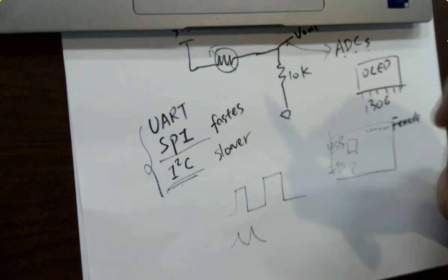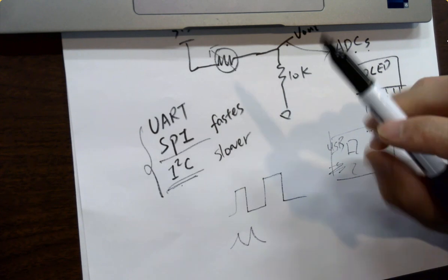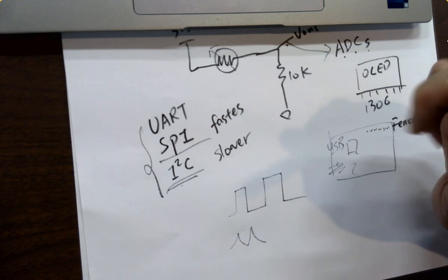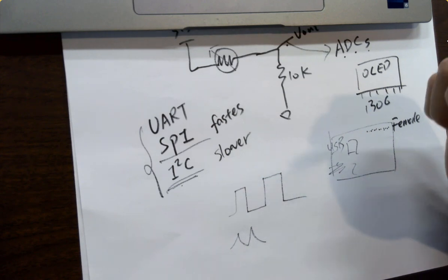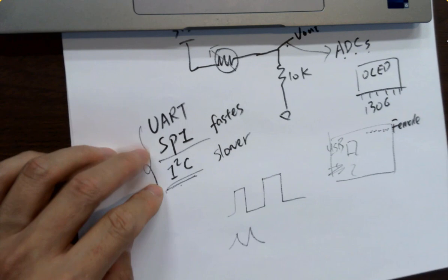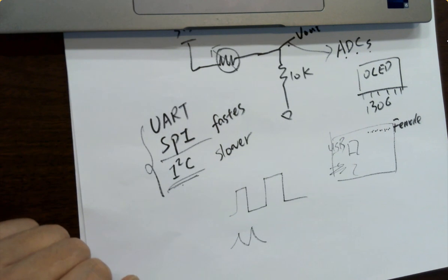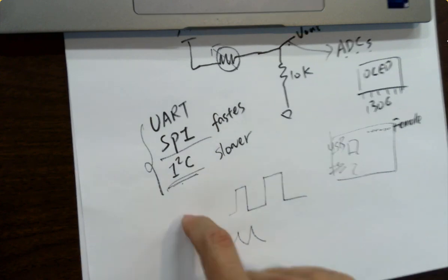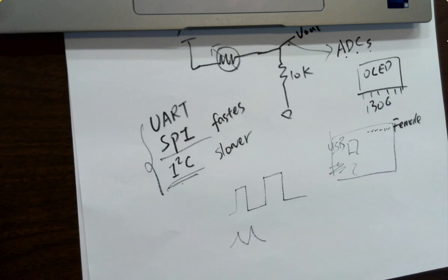If I want to transfer temperature data from a hot tub in Pagosa Springs over a 100 meter cable to a data center mounted to a pole on their property, do we want to use SPI or I2C? Is it through a wire? Yeah, it's a cable. Oh, a temperature sensor, just a sensor, doesn't have a microcontroller on it. It's just a little tip. I2C, okay? Long distance transmission.